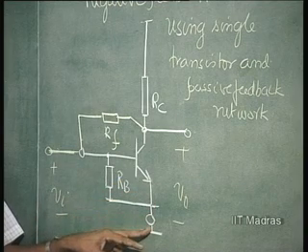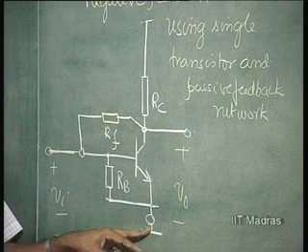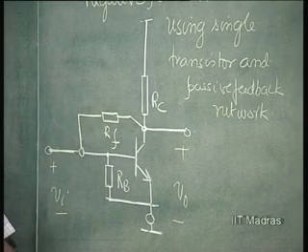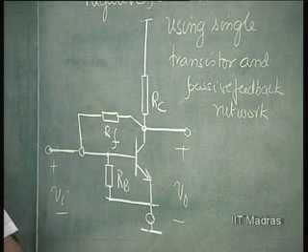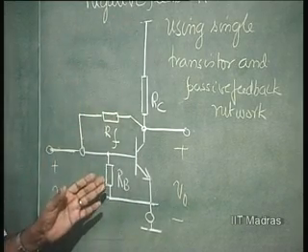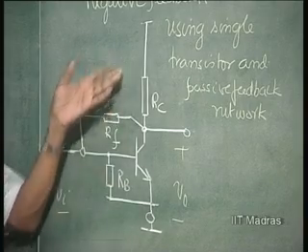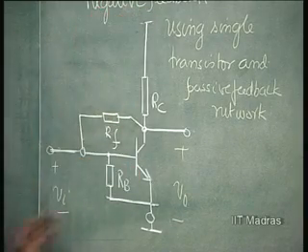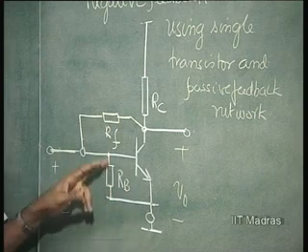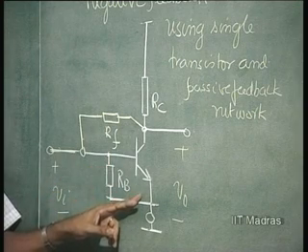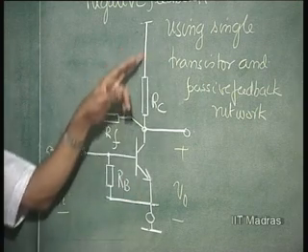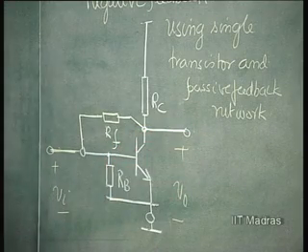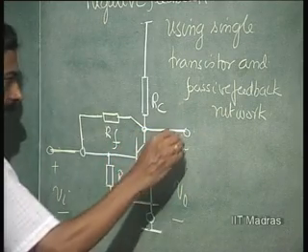So, we have emitter signal wise connected to ground, and RB is the biasing resistance which might have been used for obtaining V bias, okay, VBB for this transistor from a common supply. So, these are all the non-idealities. RB is coming here, okay, taking away certain amount of current, and RC is the load. There may be additional load resistance also connected. So, you might have this as this also.